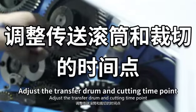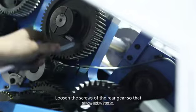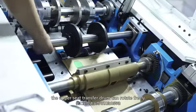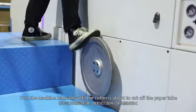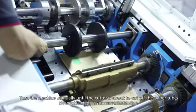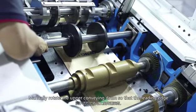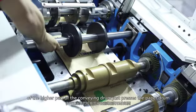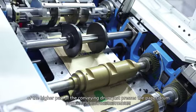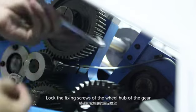Adjust the transfer drum and cutting time point. Loosen the screws of the rear gear so that the upper seat transfer drum can rotate freely. Turn the machine manually until the cutter is about to cut off the paper tube. Manually rotate the upper conveying drum so that the leading edge of the higher part of the conveying drum just presses the paper drum. Lock the fixing screws of the wheel hub of the gear.